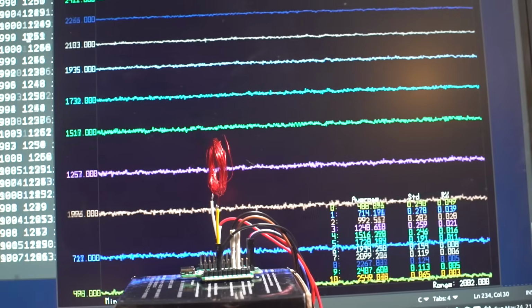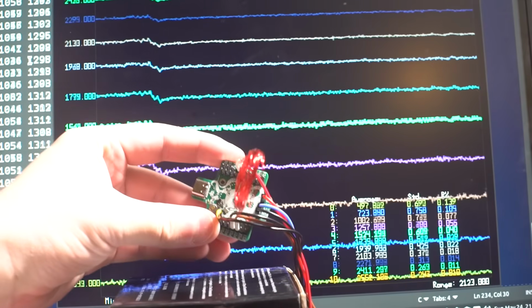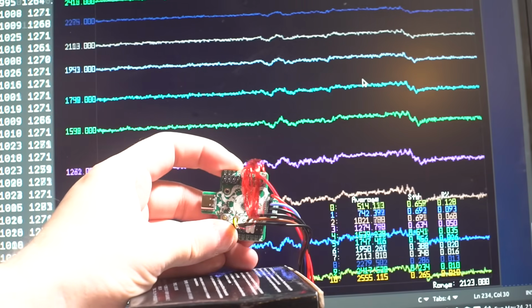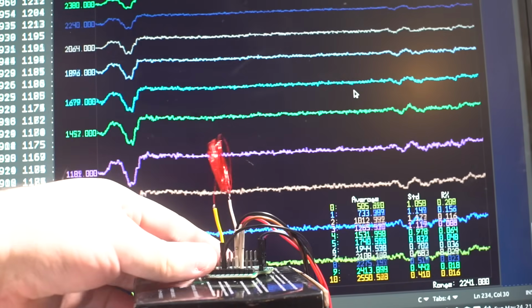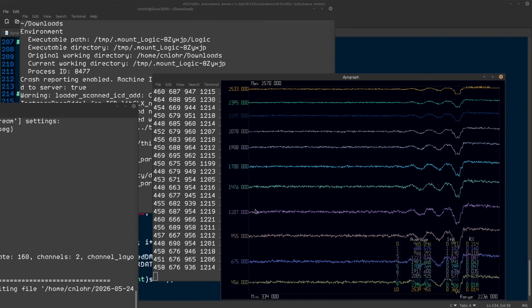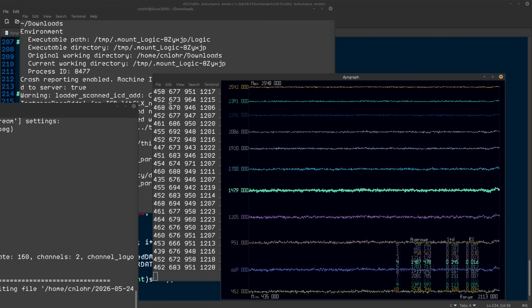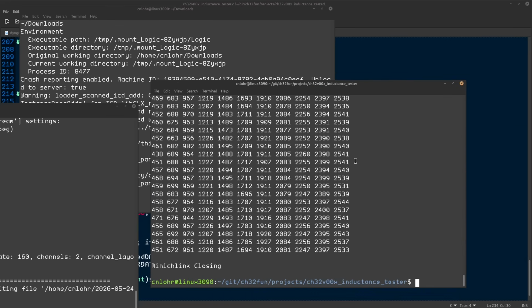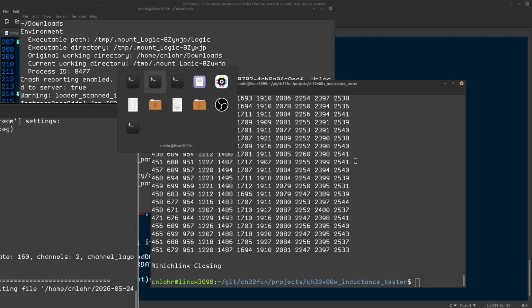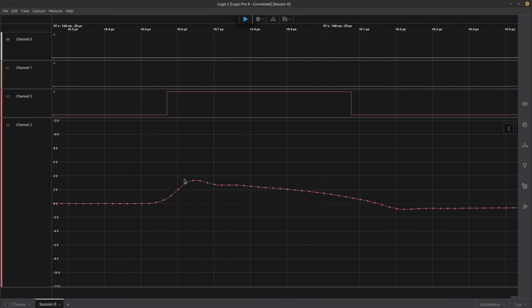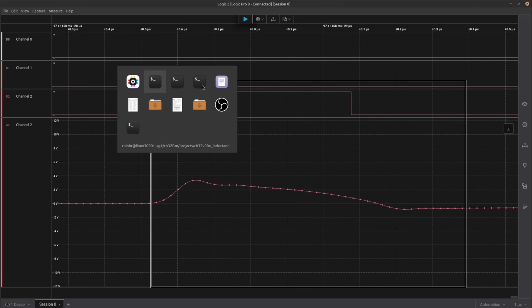Now there's a fun thing. On these little CH32V006 boards I have, there's actually a little crystal on them. That crystal will help us make the timing more precise. A lot of the error inside of an ADC is actually due to the crystal's ability to be very precisely timed. In addition, the time at which we're able to measure the point on the curve is very much controlled by how precise our clock is.